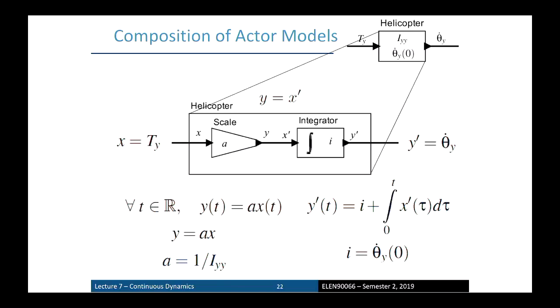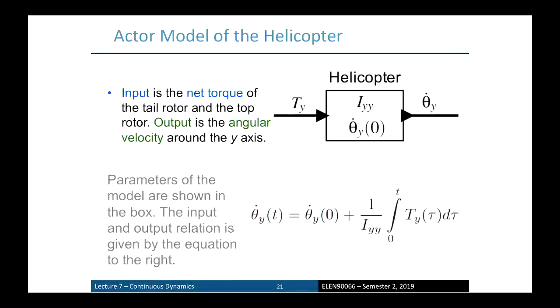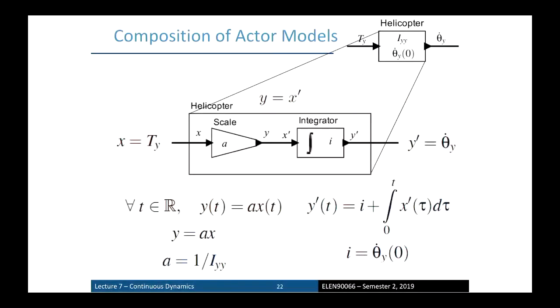Now, why is this so powerful? Because instead of trying to write out some differential equation somewhere, how do you write that in? You can write an integral equation, write it out in MATLAB in a real clunky way, or you can jump into a nice piece of software like Simulink and drop in blocks that do this for you. They are actor models, a scaling actor model and an integrator. And this also functionally represents what's going on.